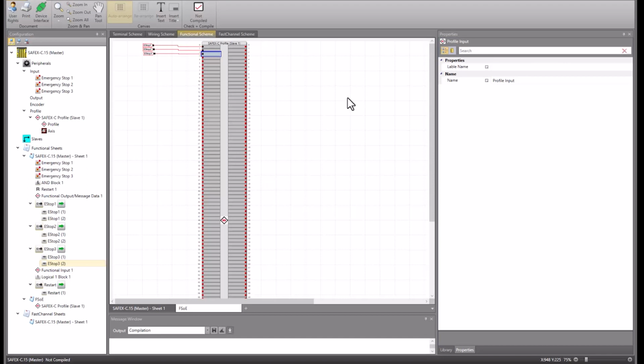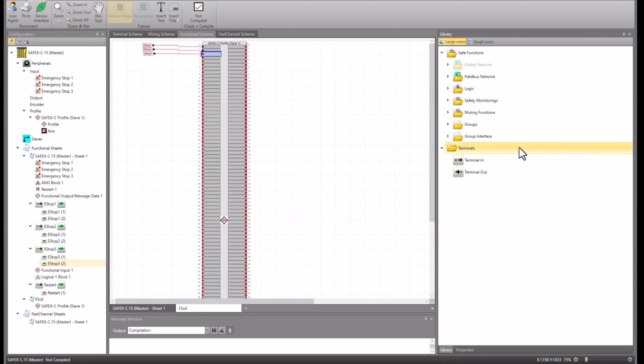In the previous video, it was explained how the functional exchange with the Control-X core works. The programs were the same for both SafeX, but from now on the programs differ. I expect now from the FSoE slave also 3 emergency stop signals. These can then be used.